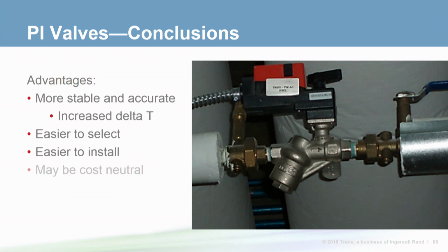And considering the price premium has been steadily dropping, pressure-independent valves might be cost neutral if all costs are considered. So are pressure-independent valves worth it? If you're not sure you can get a high-quality, properly selected, location-specific valve installed on a job, then by all means specify quality pressure-independent valves. It should be well worth the customer's investment.